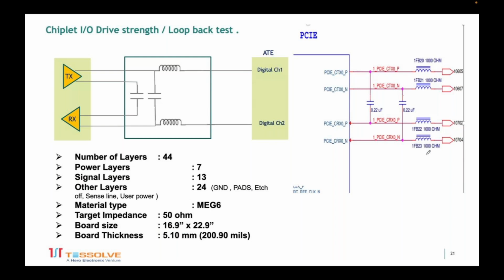In the event that the drivers of the DUT are very weak, now there are MEMS based loopbacks, which are very, very small. I think ADI and a few other companies, Korean companies, are making a differential loopback, just capacitor coupling or with inductance, so that the transmission line properties of the device are kept intact. So we could look at MEMS based loopback implemented in the load board for better performance.